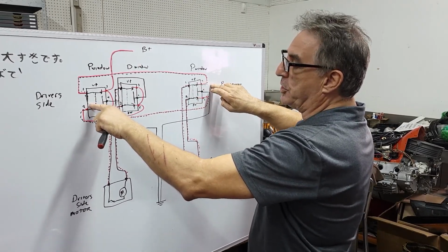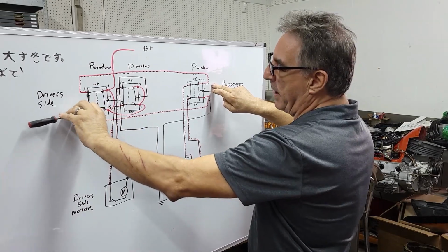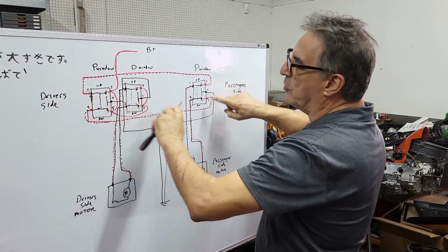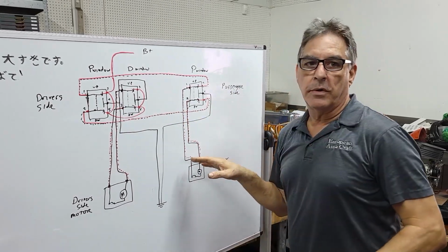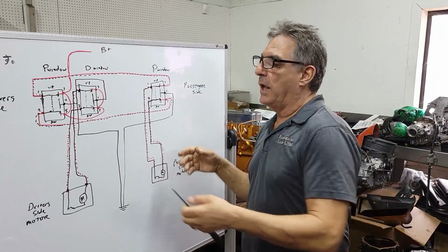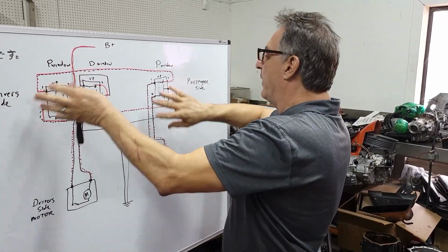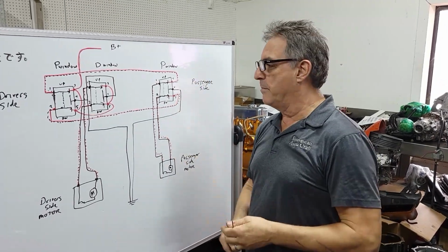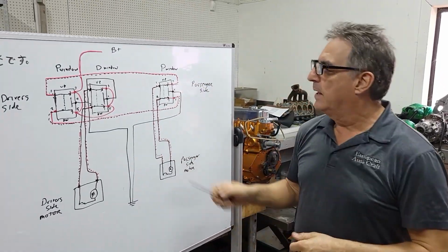If I put the switch up, I now take my 12 volt signal and it goes to ground. So now we have 2 grounds going to the motor instead of 1. And that'll make the window stop. If we both go up at the same time, the signals all stay the same and the window just continues on its merry way in either direction.